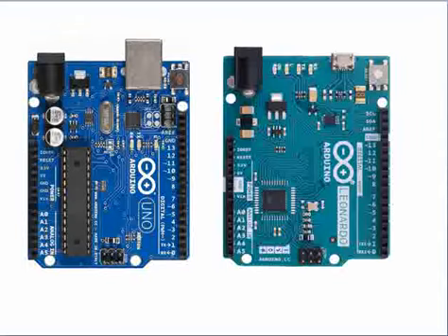And then in the Arduino Uno family, there are many boards. So in that one family, we just compared two boards at a very high level. If you see both the boards, we have talked about Arduino Uno, that you have a USB controller chip, and then you have an ATmega328P. But on the Arduino Leonardo board, you have a single chip which acts as both the USB controller and the main controller. So it performs both the functionalities.